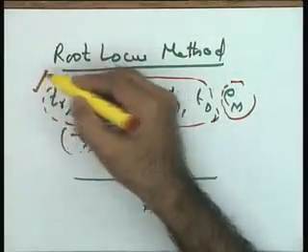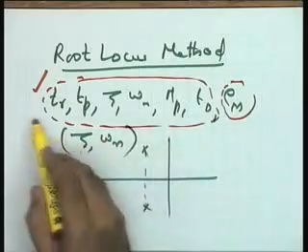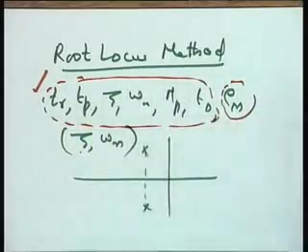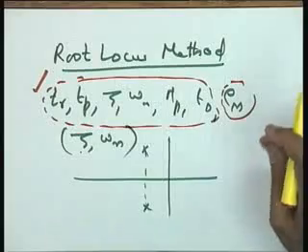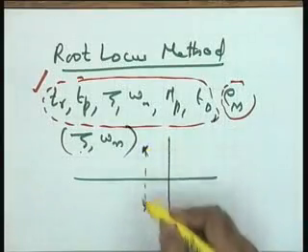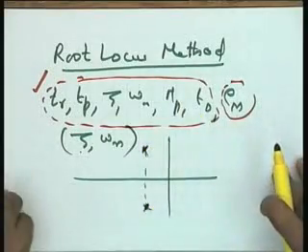So, this aspect we will see in our design examples. Given any of these attributes, you can take them into account suitably, so that the performance can be translated into a pair of complex conjugate poles. And whether your performance is satisfied or not, it is more appropriate to see in terms of a root locus plot than any other method.